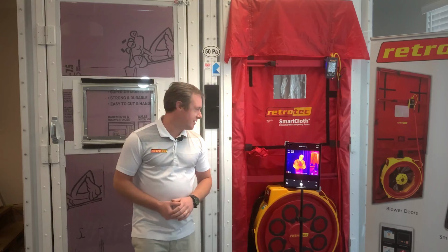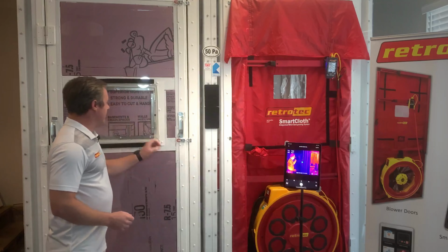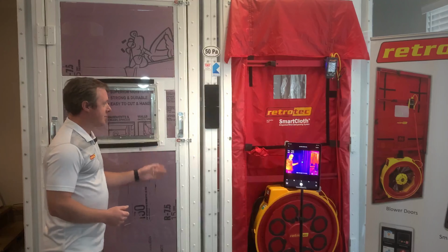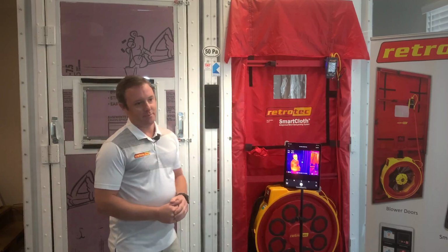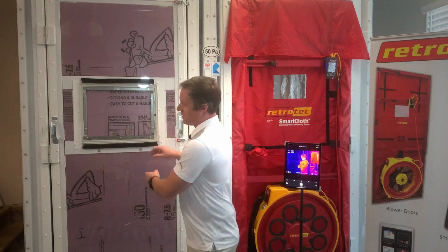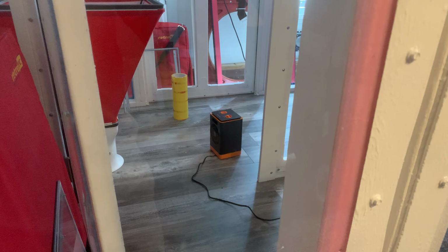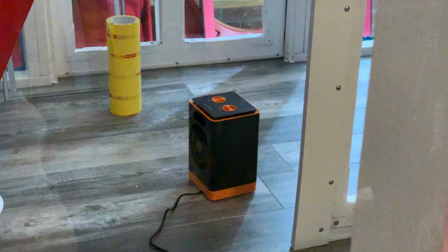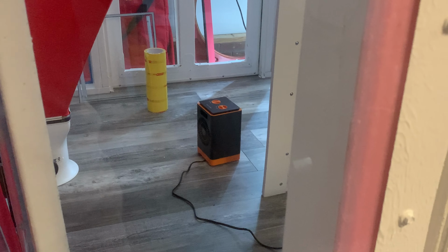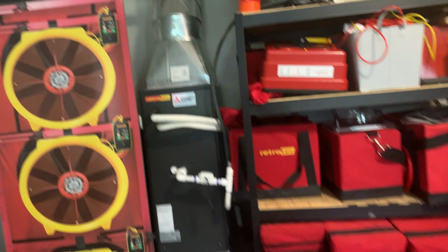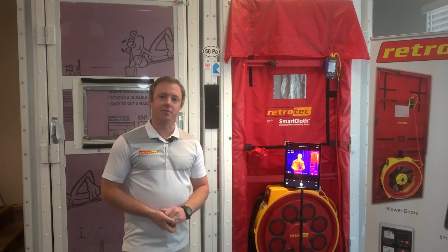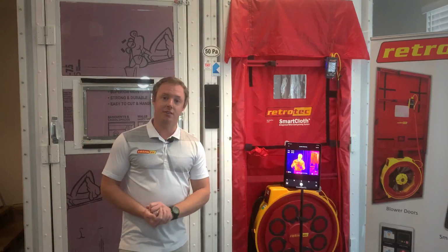And what we're going to test is my airtightness test simulator here, and we are creating a delta T between inside the chamber and outside. So basically what we're doing is creating heat inside and cooling down the space around it. That way we're simulating a house in the winter season, creating that good delta T so that we're getting a warm interior and a cool exterior. So here you'll see that we have about a 20-degree delta T.